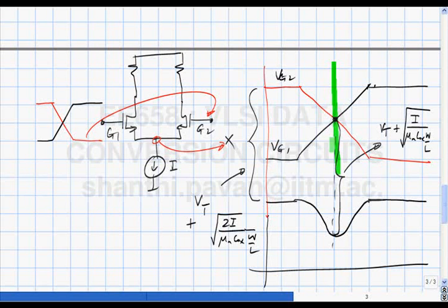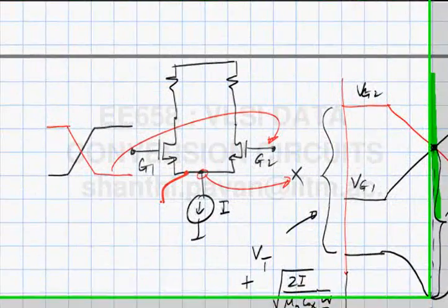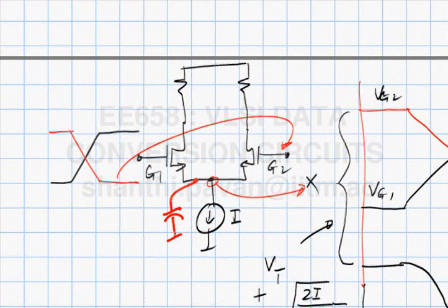Okay, so this is assuming that these are all slowly varying, right? So if you put a gentle ramp, that's the voltage. So we have basically neglected all capacitive currents. Okay. In practice, of course, there is always parasitic capacitance at this node. And why is this parasitic coming?